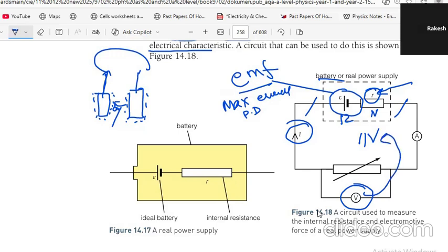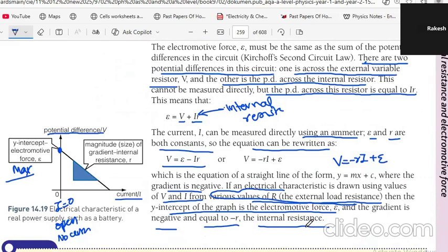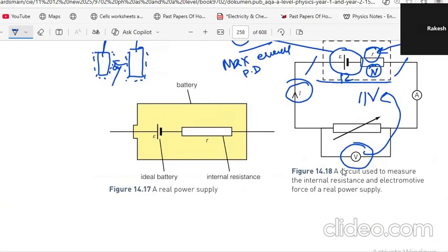Some energy it uses for itself, a very small amount. So the available energy outside is less. This is what he's saying: the total maximum is this, this is for the outer circuit, but this is for itself. Now the problem is this is not fixed. This depends on the current flowing, and the current depends on many other factors. It depends on the resistance here also. Understood?